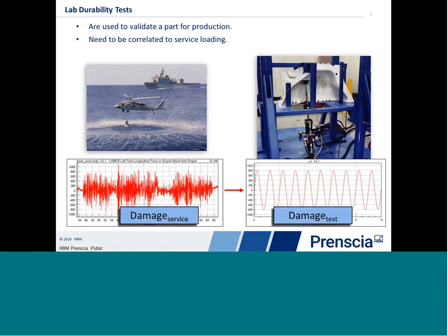We may want to cap the loading that we see in the lab at levels that are seen in the field so we don't risk changing damage mechanisms or failure modes. We may use fatigue damage concepts of equivalent damage or equivalent fatigue tests.